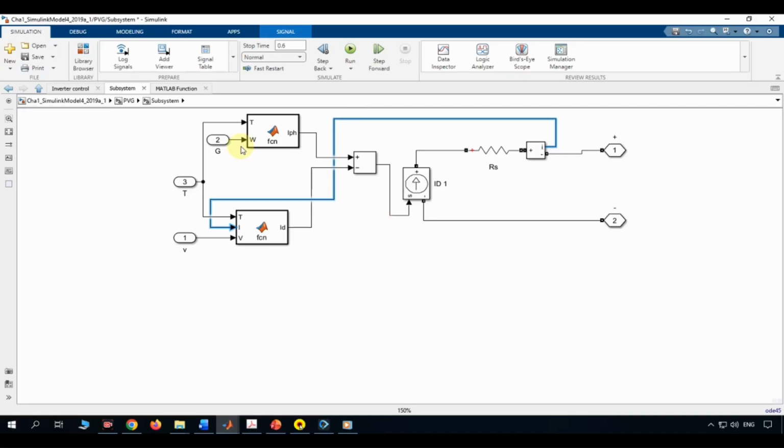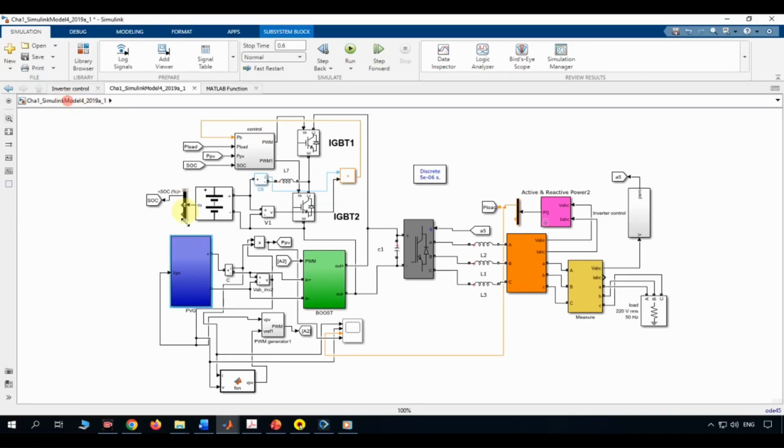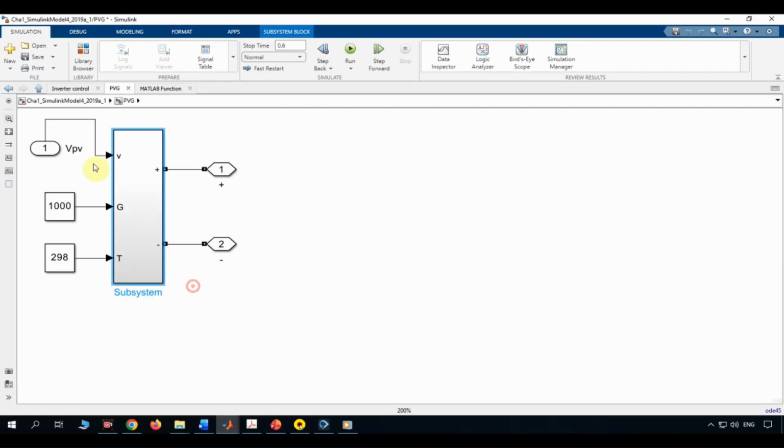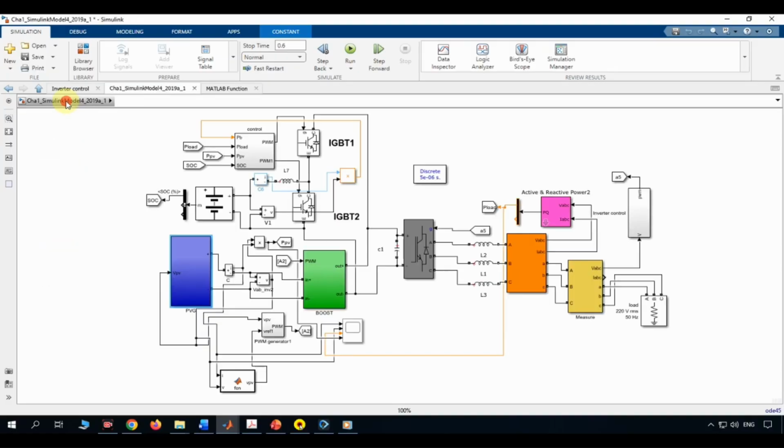So to summarize, this innocent-looking blue box is running the full single-diode solar cell model: photocurrent from one function, temperature-corrected diode current from another, combined through a real current source and series resistance, with a feedback loop closing the physics. Change G and T on the mask, and you're simulating your panel under any sunlight and temperature condition you want.